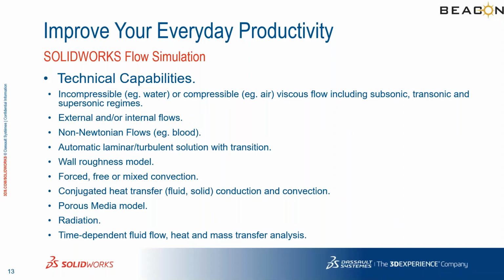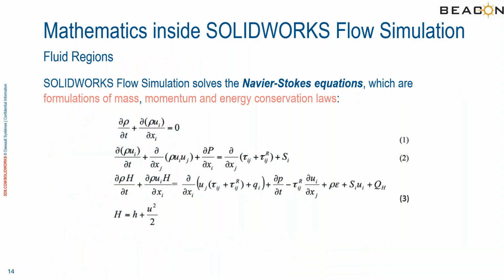We can play with different types of fluids, such as Newtonian and non-Newtonian fluids, and we can specify any conjugate heat transfer problem that we are facing, or radiation problems, and we can do time dependent fluid flow analysis as well. And of course, the mathematics behind it solves the Navier-Stokes equation, which is the formulation of the momentum and energy conservation law.